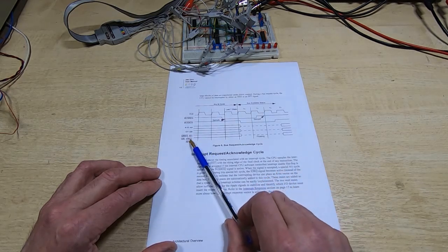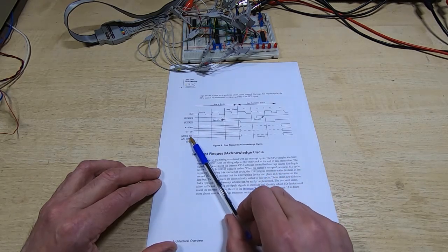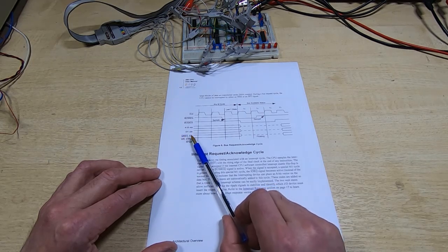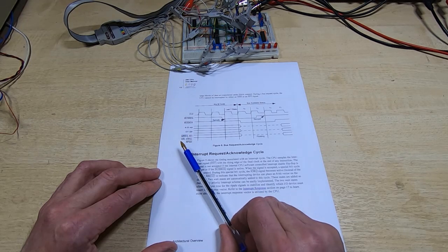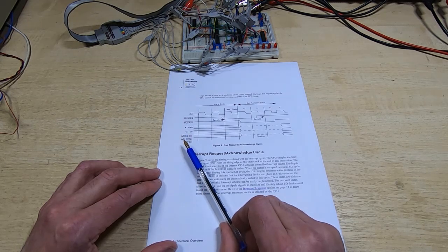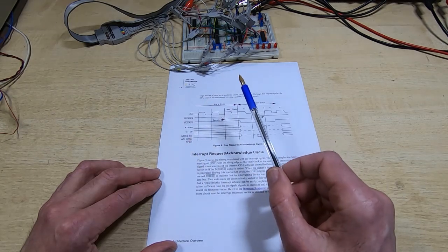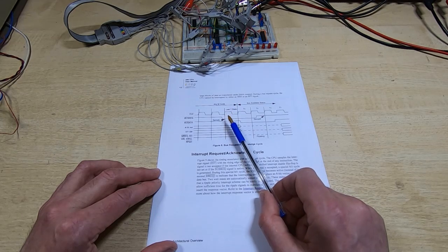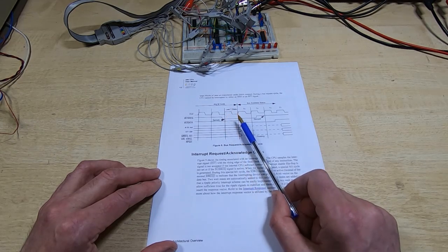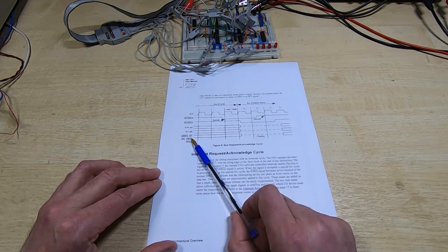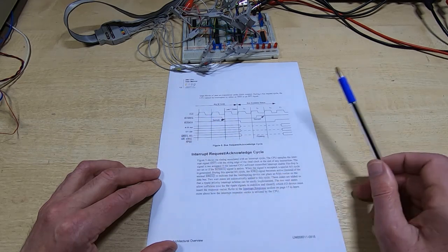We will need to make sure that the other 4 lines are properly handled. We will be making use of memory request, read and write, because we'll be transferring data from and to RAM, and although we're using in-out to access the floppy drive controller chip, we're not using it during the actual DMA transfers. But we will need to make sure that the in-out request line is handled, otherwise if we leave it floating it could cause problems.